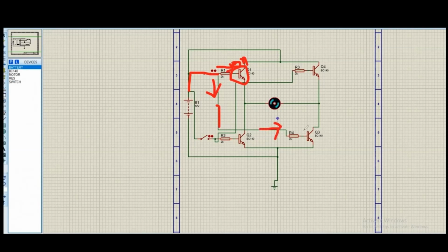It will also turn this transistor on. When these two transistors are on, they will allow the voltage source applied here, connected here, to act. The current will start flowing, and as the transistor is in the on state, it will behave as a short circuit here. Now the current has two paths, so it could move towards the right or downward. But in the downward position, the circuit is still open. As there is no current on the base, this transistor has no current on its base, similarly this transistor. So they will behave as an open circuit.